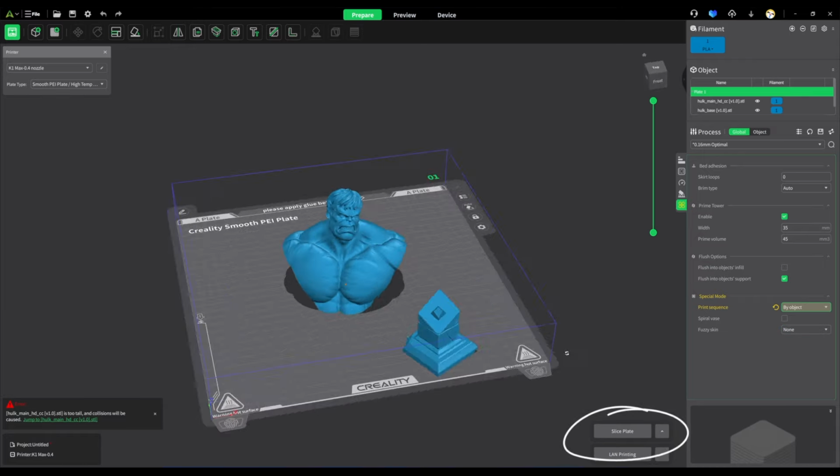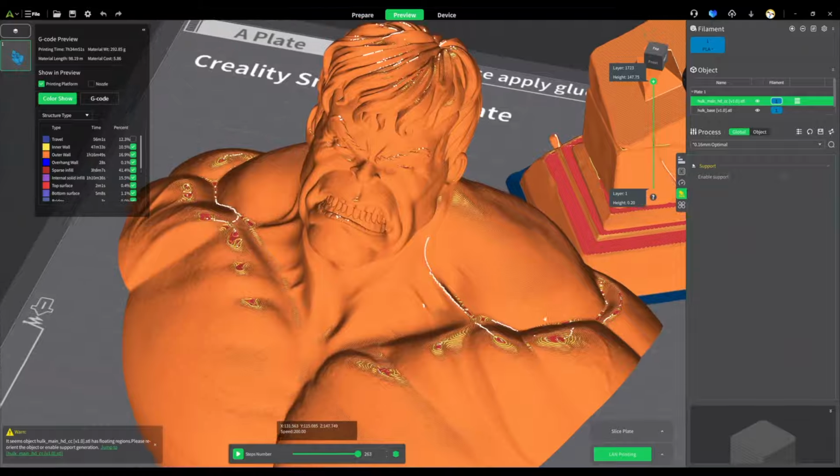Another bug here is related to adaptive layers. Adaptive layers is a mode where you can tell the slicer to vary the height of each layer, making organic parts smoother, and avoiding that kind of layer line that you can see, especially on the head of action figures and things like that. That layer that you can see clearly that this is a layer of 3D printing from an FDM printer.